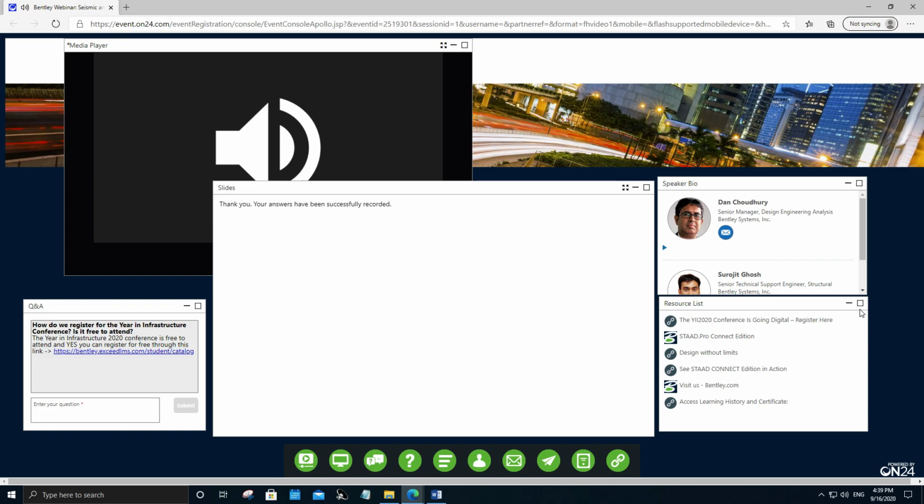There is one question: does the software support the UBC 97 response spectrum? Yes, I think we have the option, but UBC 97 is very old. Still, it is there, I think. If you want to use the latest one, the ASCE 7-16 code, then you need to use the CONNECT Edition version, because it was not implemented in the earlier version. But if you want to use the older 97 version, it is still available there.